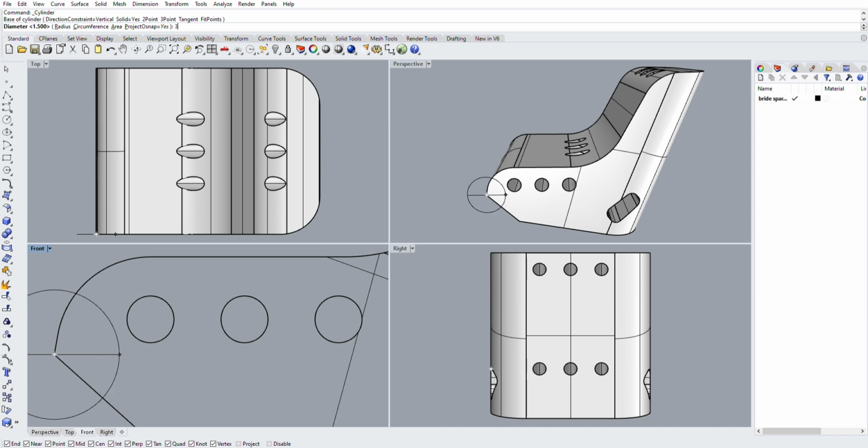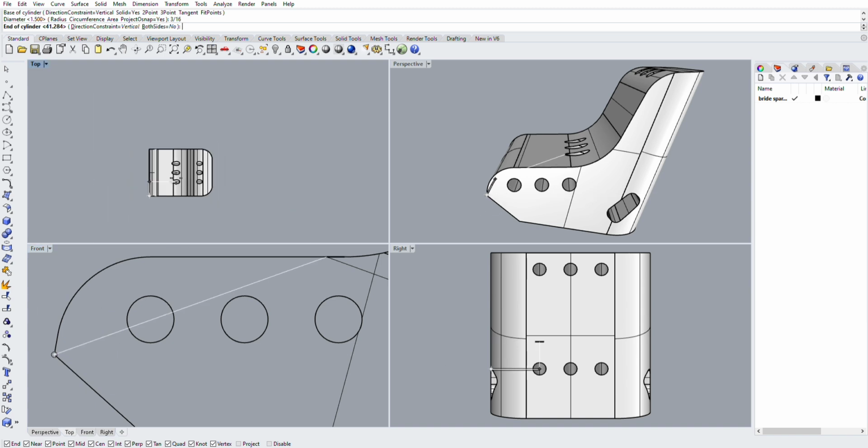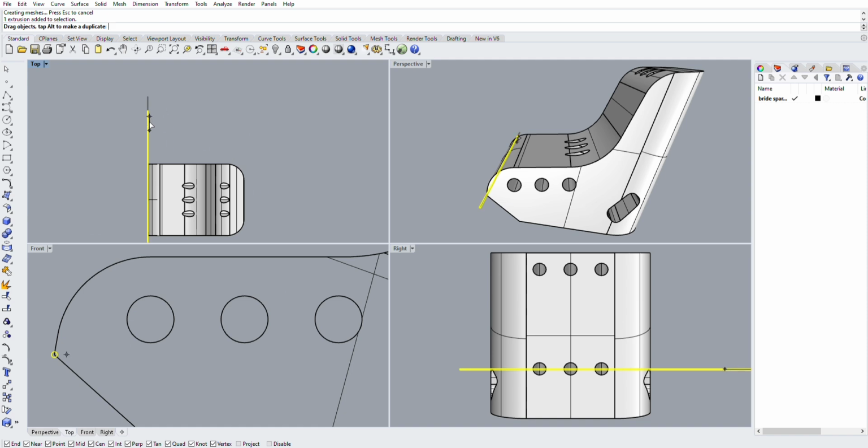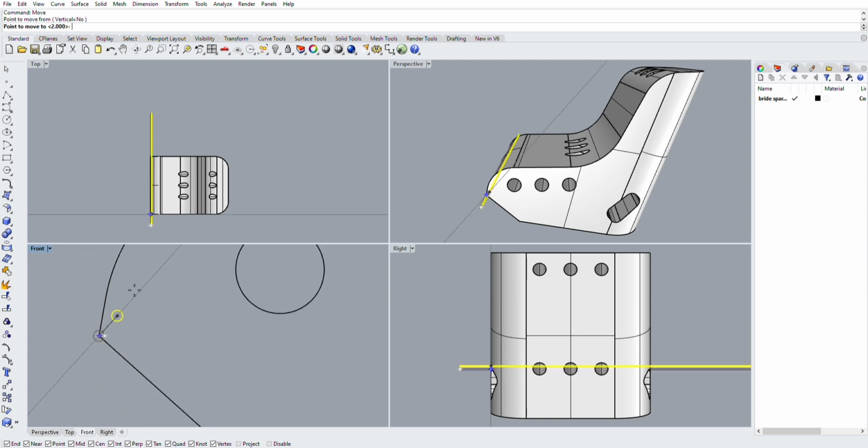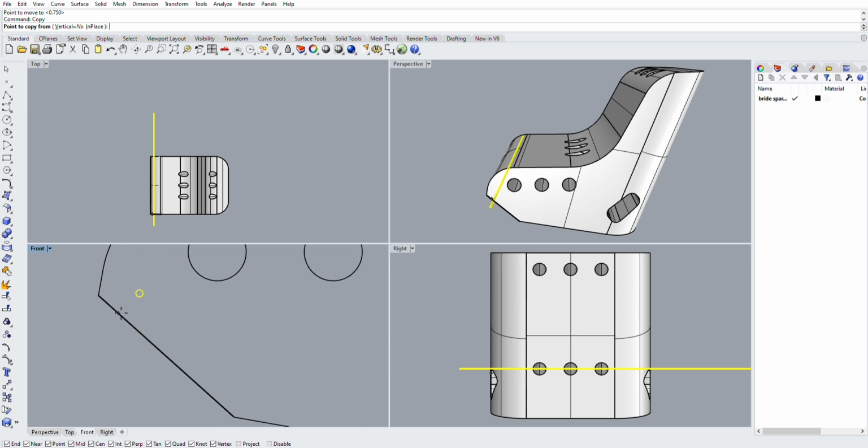Now, one of the advantages of the CNC table is that I can punch my dimple die holes, I can punch shapes, my seatbelt holes, I can punch just about anything. In this case, I'm going to mark all of my solid rivet holes. And part of the reason that I copied this over to the other side is that I don't want the solid rivet holes in my base. I only want them in my outer structure because metal does not work exactly like it does on the computer. Not the way I'm using it, so it's nice to have a little bit of room for error.